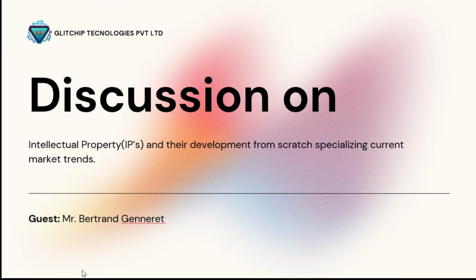Yeah. So let's take an example. I don't know if the video will be fine, if you can see it clearly, but I will explain anyway. So this is just a block level picture of a serializer, deserializer, SERDES. This one is a hard IP because it is done for TSMC. It's TSMC 7 nanometer node, and this SERDES, if we talk about specification, is a 56 gigabit per second SERDES.